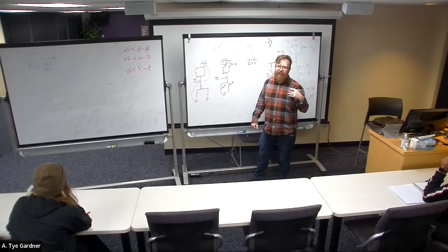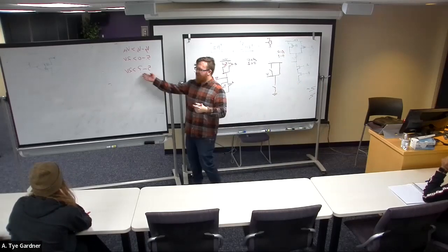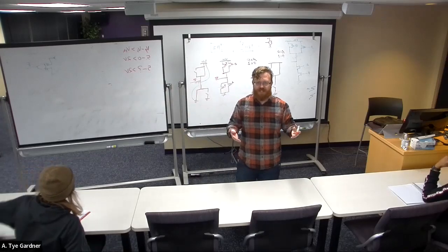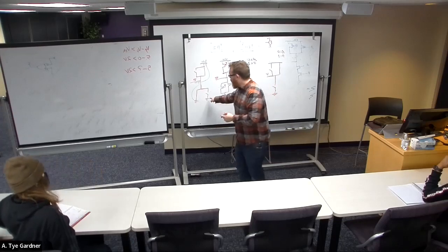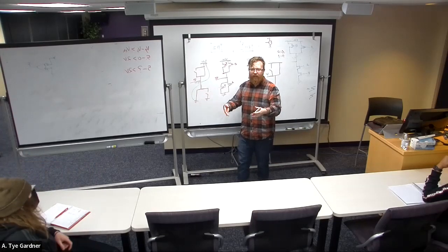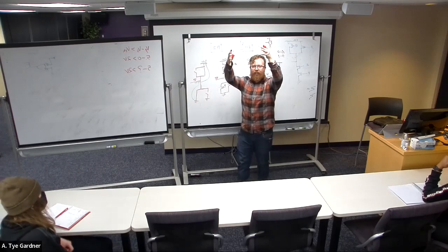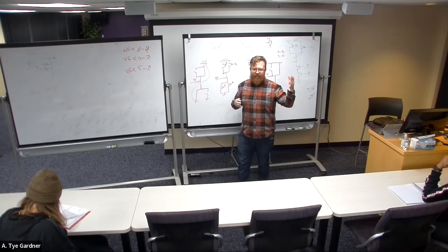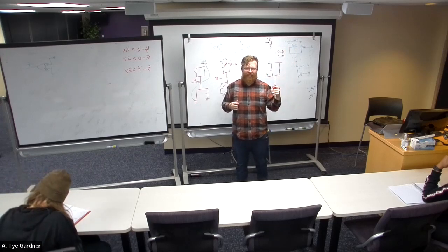Gotcha. Cool. So we're throwing in I don't know, which is why it gets so confusing sometimes. Sometimes it works the first time because you have no voltage here, but because it's just kind of floating, you're not holding it to ground, then it drifts up to a higher voltage, and now it's no longer ground and it stops working. So you can have actually intermittent functionality.